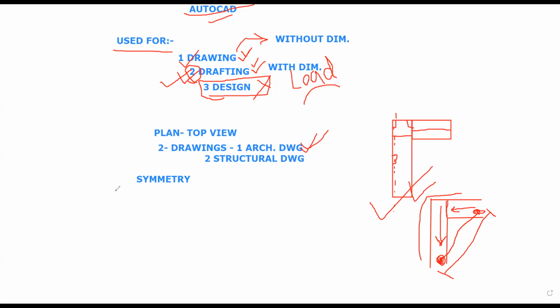Okay, write down some rules before proceeding with this. Write down some rules for column placements. Write down the first rule. Column positioning. The first and foremost rule: people will be telling you the column to column distance should be this much and that much. So I am telling you, write down: spacing between two columns can be between 10 feet to 16 feet.